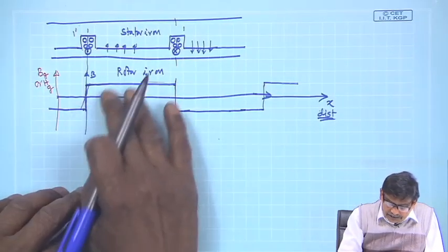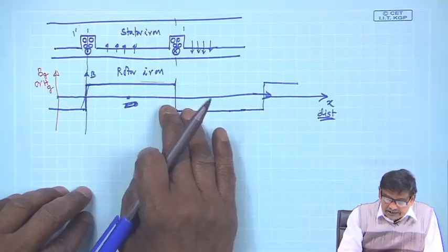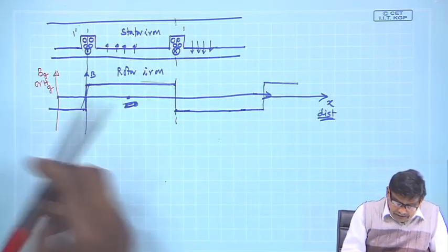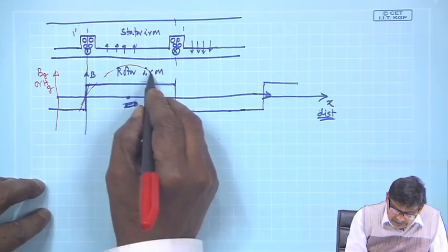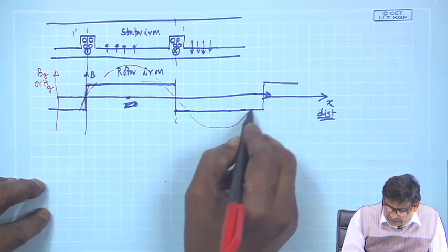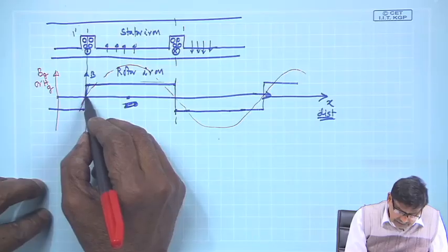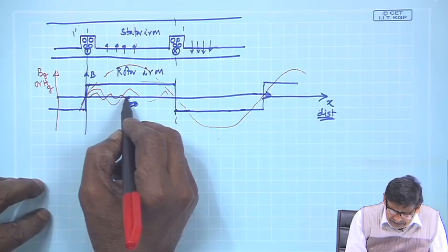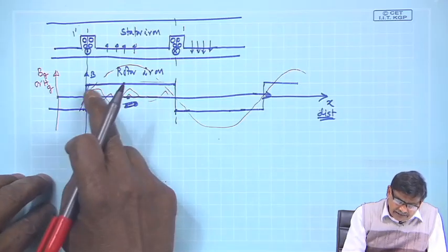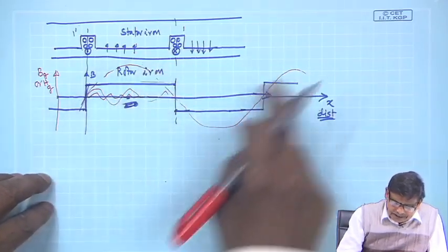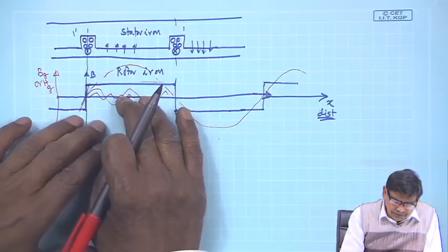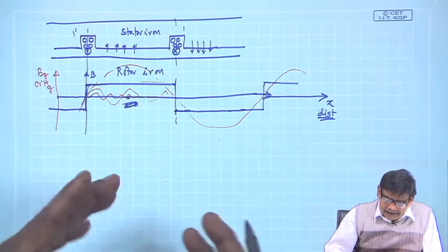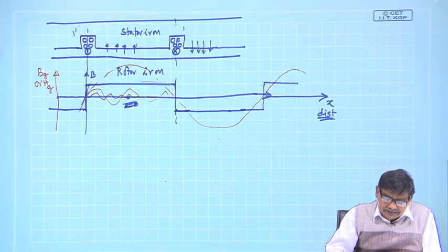For example, if such a square wave voltage is applied to an RL circuit, how to analyze that? I will Fourier analyze it, get a fundamental, then third harmonic, then fifth harmonic with reduced amplitude, and for the fundamental I pretend that these amplitudes are too small compared to it, their effects on current will be less, and you accept that this is a sinusoidal voltage.